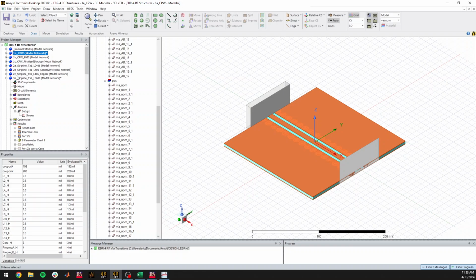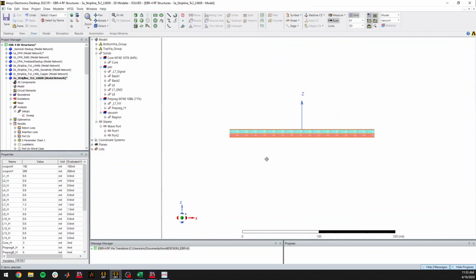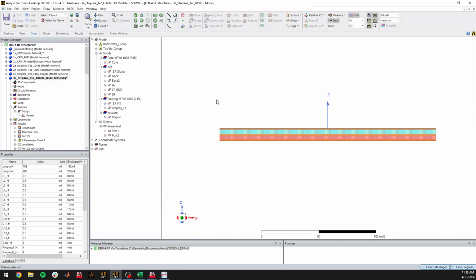We're going to move forward now and show the stripline structure that's being designed, which is a very similar design process, where this is just a cutout of that 14-layer board. It's using, in this case, I believe, layers 6, 7, and 8, where 6 and 8 are the ground pours, and 7 is the signal layer, which also has a ground pour in it.